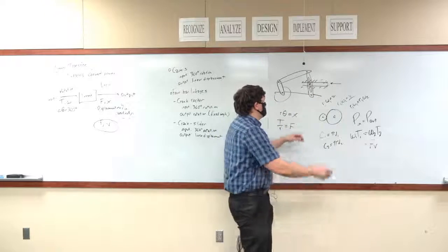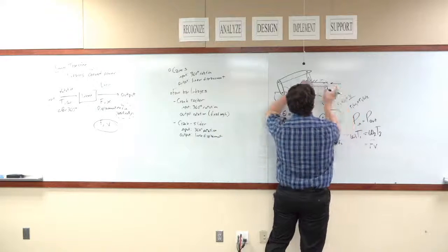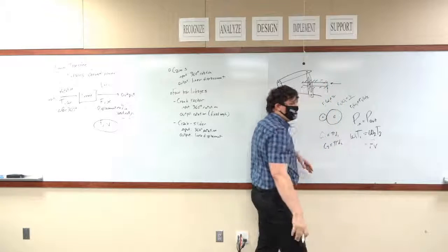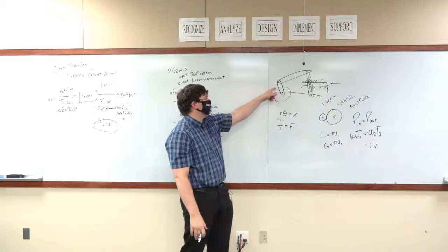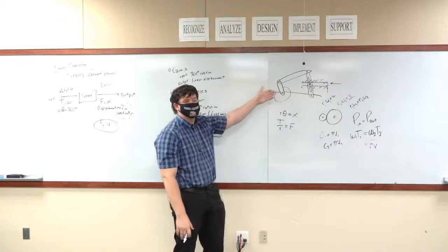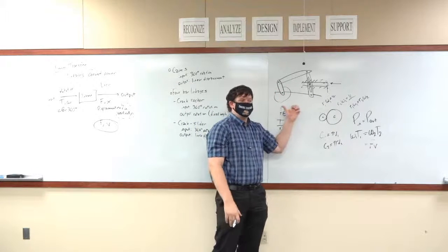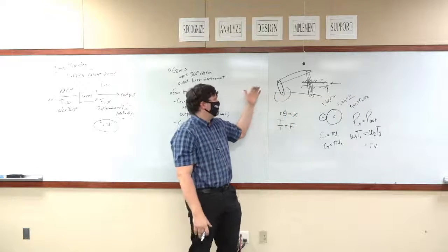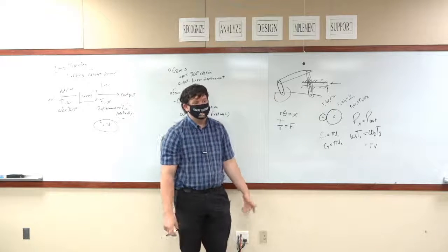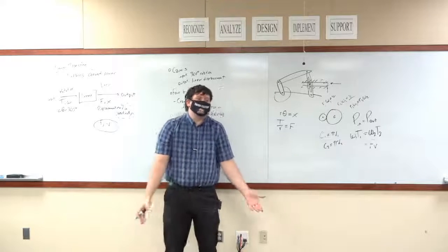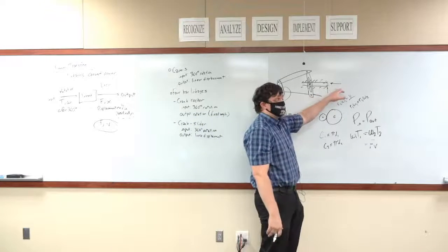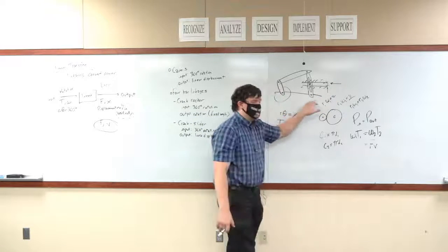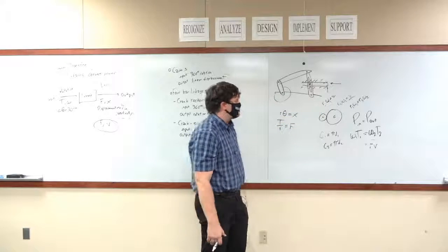Now that said, if this thing gets hit here and it causes the rocker to rotate, well, that's your worst case scenario, because that's basically having a crank slider system where your force is pushing on your slider directly perpendicular. Okay? That is the worst case scenario. There's nothing you can do about that. But in this case, the force direction means that this can be carried by this rocker mechanism.